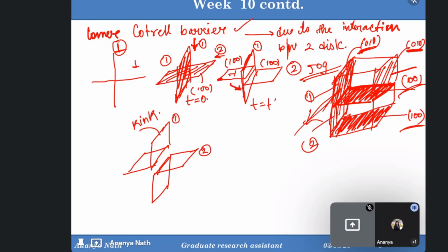So we have a unique designation system which is valid for all the lattices. It's like 010, 101, or 111, this type of designation, so that if you are talking about a particular plane which will have the same property throughout the lattice, you can identify it. Because depending upon these planes, different materials have different characteristics.